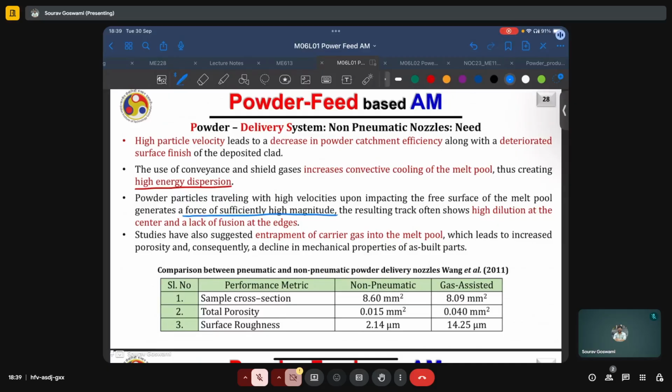And these liberated gases, if they are far away from the surface, tend to get concentrated in small regions known as gas pores, leaving behind small, almost perfectly spherical voids. But then again, focusing on the macro picture, these voids will result in part from the use of the carrier gas for delivery of powder particles.